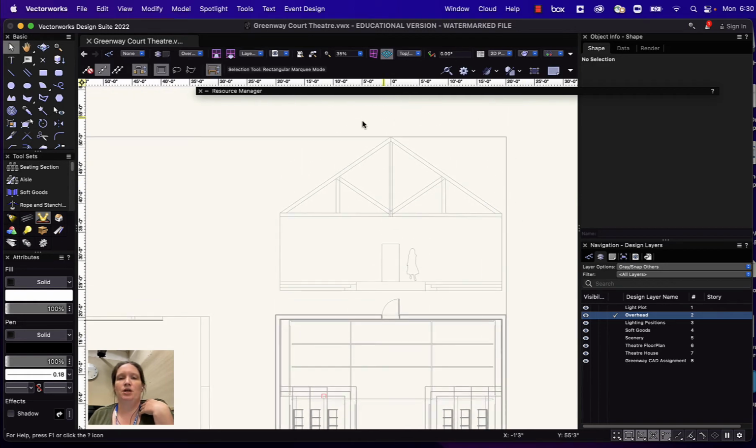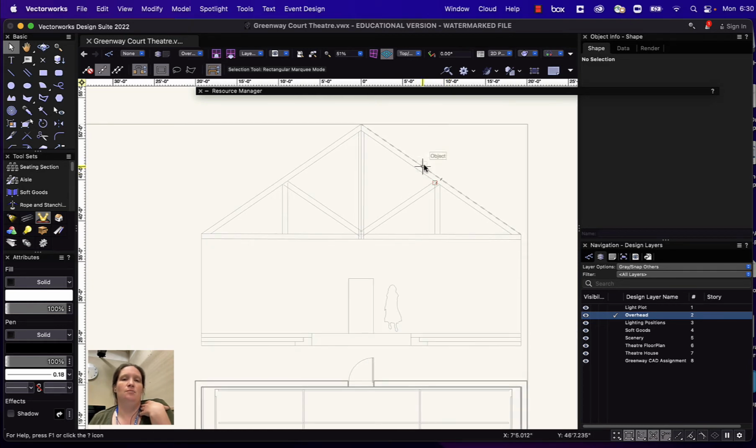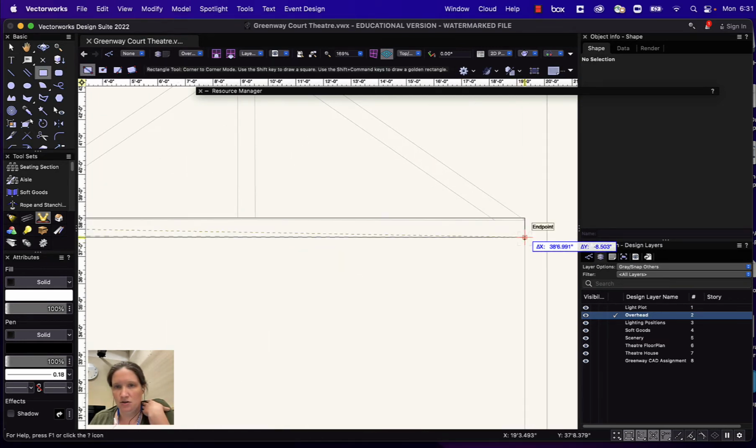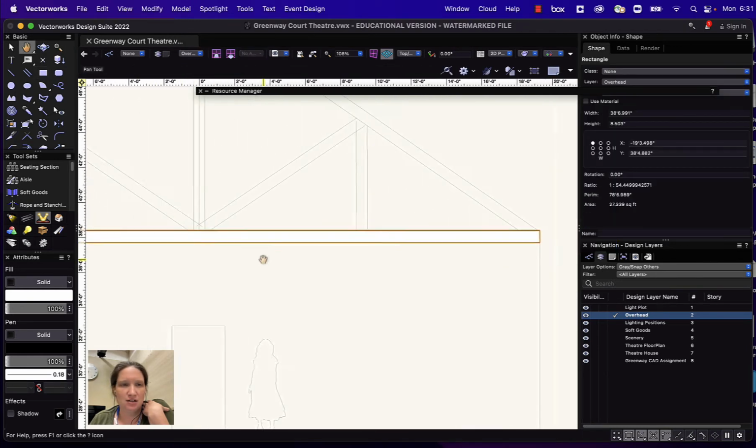So they're pretty well drawn in the existing drafting. You have 2 options. You can either really get these shapes, or you can just create, using the polyline tool, a single shape. That's where I'm going to go with this. So that I have the simple shapes that go together into the full object. And then I'll extrude it all at once. So I'm going to start with a rectangle here, tracing that bottom edge.